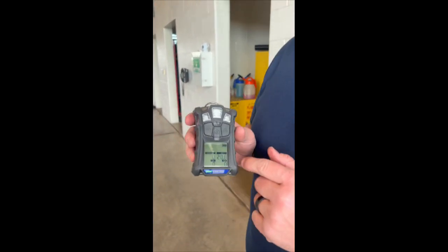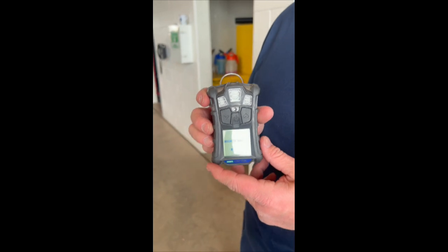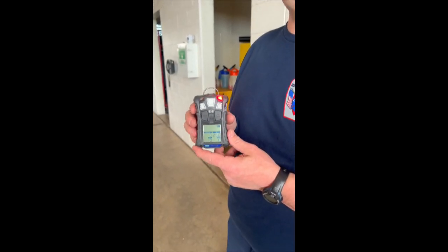So this is the MSA monitor. It's a passive monitor, meaning it takes a small sniff of the area you're in, versus the Q-ray monitor, which used a pump to draw air directly into the sensors. This one, in order to use tubing or to monitor remotely, requires an external pump, and that would be provided by Hazmat. Hazmat 50 and Engine 50 are part of any confined space or trench rescue response, specifically for that purpose of monitoring, as well as chemical interpretation for whatever environment we might be operating in.